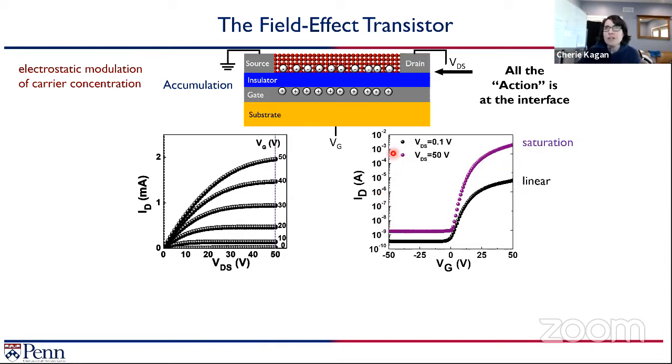And so that's why I showed you this here, where we get more than 6 orders of magnitude in modulation between the off and the on state. And this happens to be a cadmium selenide nanocrystal transistor. The reason, by the way, that this is called the linear regime is that if you look in this region here, all of these characteristics are in fact linear.